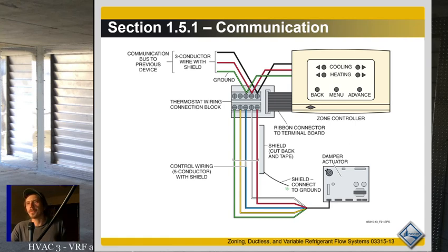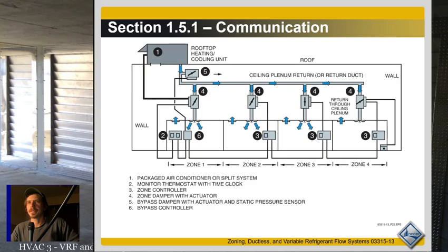In general, the issues you would have with shielding both ends aren't common enough, or common at all, in HVAC systems to where it's a problem. It's just a nice thing to note.